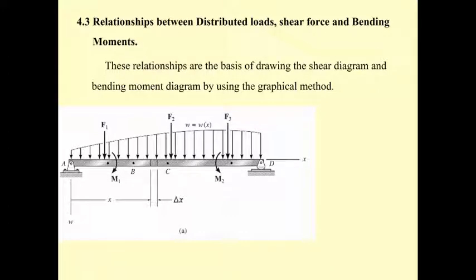After we determine the reactions, we draw the portion of the beam that's cut at a given point, and at the cutting point we will have the normal force, shear force, and bending moment due to the applied load. Then we use the equations of equilibrium again. We can determine the normal force, the shear force, and the bending moment.